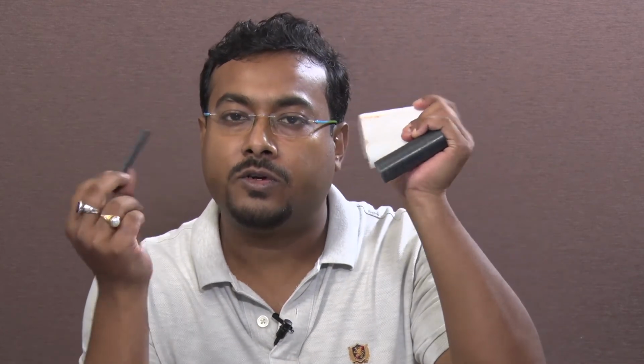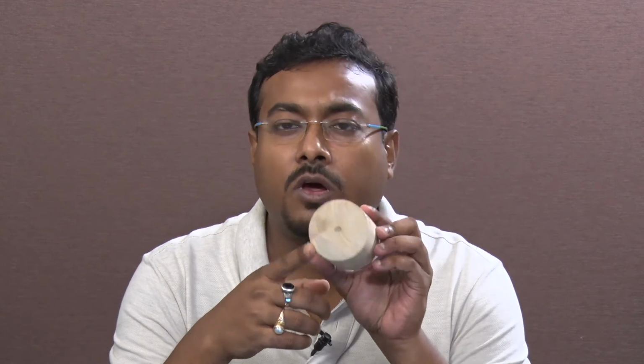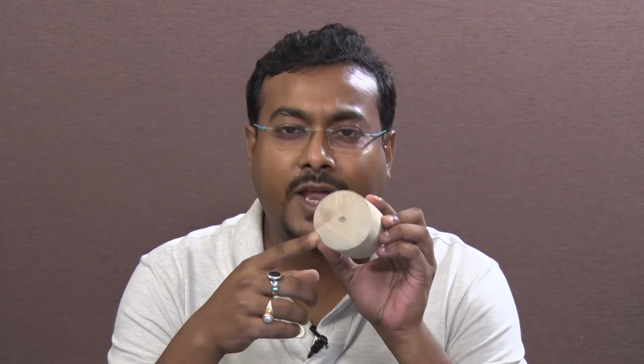We also can use different kinds of nylon bars with different diameters. We can turn them on a lathe machine, or we can directly use them. We can definitely use wood. Wood is used most of the time when the actual product is made up of wood, because you cannot give the actual texture of the wood by making it with plastic. You can definitely try, but you will not get the exact texture of the wood. But you can make it with plastic, and then on top of it you can take a printout of a similar wood-like print, and paste it on the surface of the plastic.